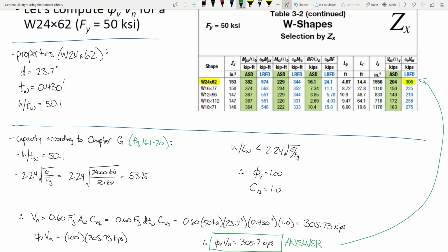Let's put a stiffener here. And let's say that's my support. So what happens is, if you load this thing in shear, as we saw in that video, it buckles, right? But when it buckles, the web sort of folds in this way, and we develop this rippled region that goes like that. Y'all remember seeing that in that video where it kind of ripples like that?